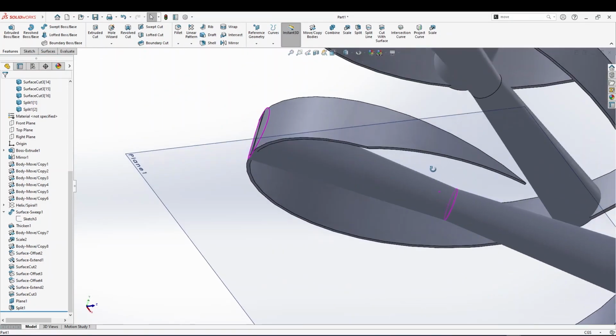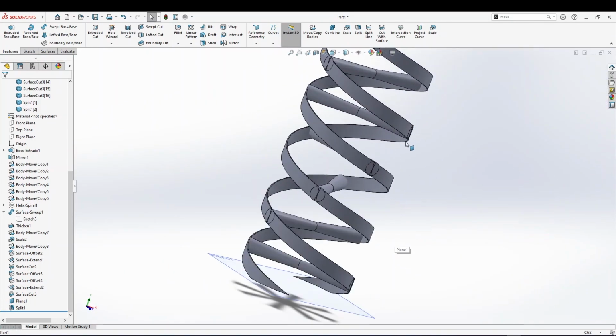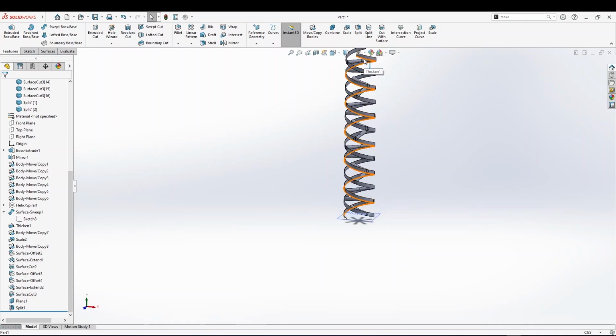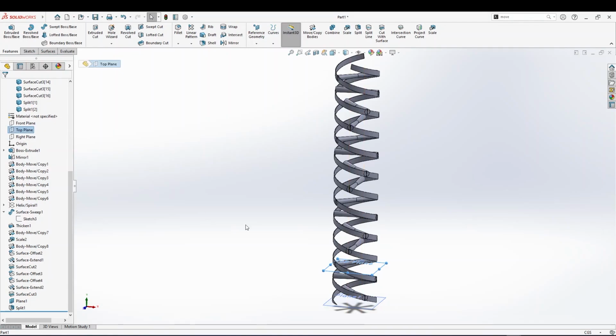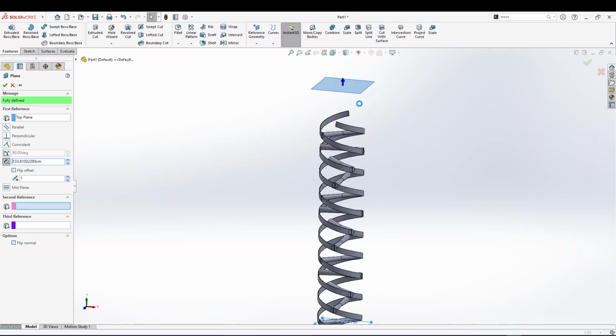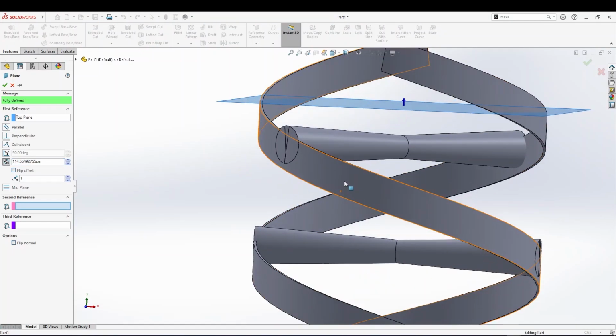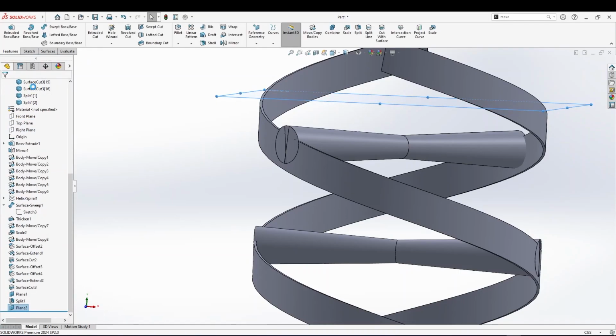As you can see, now it's a planar face, because it was a cut with a plane, and everything will work perfectly for us. Now we want to do the same here. So we started with this plane. It's the top plane. Again, take it, press Ctrl and drag it up with Ctrl. Here you also can rotate the mouse wheel. Just do not release Ctrl. Again, you hold Ctrl all the time. Once it's free, just make one normal distance here, maybe 114 or 115, something, without too many decimals.